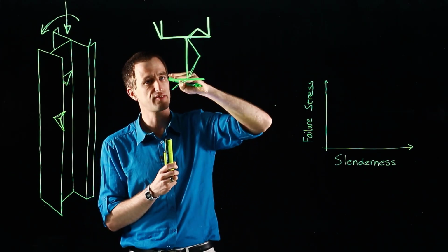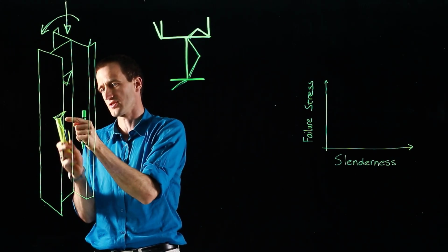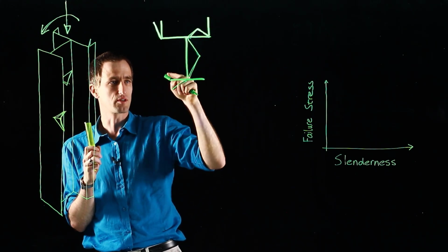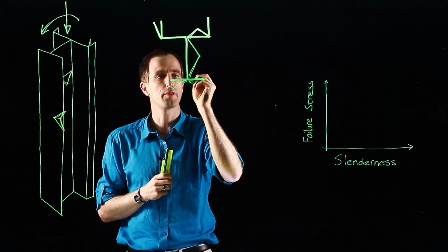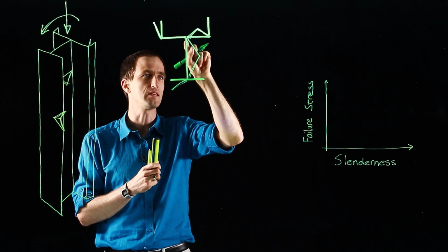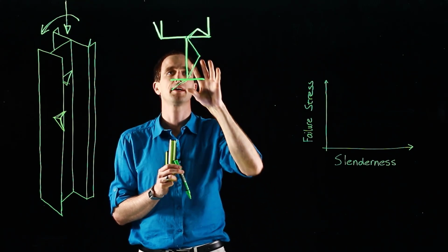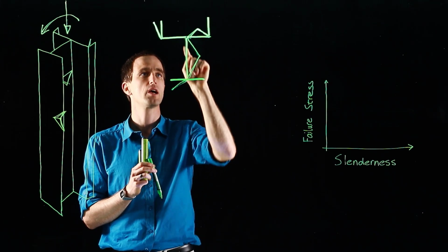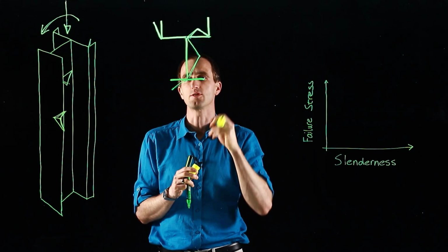Here, the entire flange just sort of pops out. You load it, it's a thin section, the entire flange just pops out. So then the furthest away from the support, the cross-section goes the furthest. But if we have a web, we have more support. We've got support there and support there that is preventing it from buckling as much. So now we've got almost a V or a bulge out in the section. So that is a lot stronger. So what you find in the calculations is that it makes a very clear distinction between supported along one edge and supported along two edges, because supported along two edges is a lot less likely to experience local buckling.